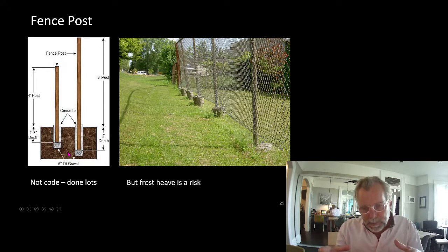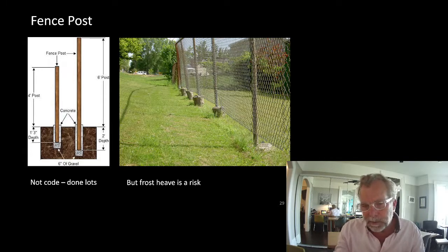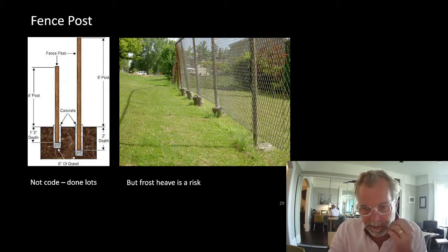The diameter of the sonotube is just enough to get concrete past all the way around. So we have a 4x4 post on the diagonal. That's going to be 6 inches on the diagonal. We want, say, 1.5 inches concrete cover. It would be a 9-inch or 230 millimeter sonotube that you'd need for a 4x4 post to get concrete around it.